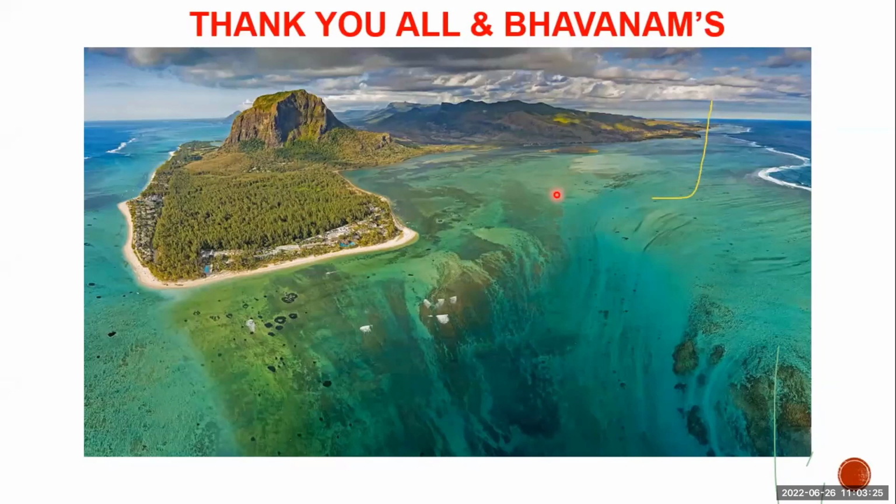I think they did the permeability test to check whether, if they do the extraction in future, any groundwater or rainwater infiltrating could contaminate nearby rivers or groundwater. That's why they check the falling head permeability, in my opinion.